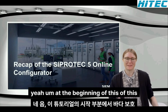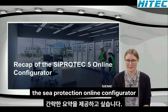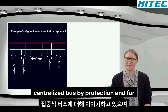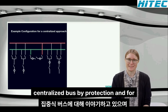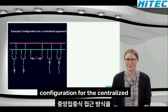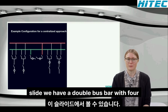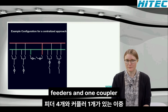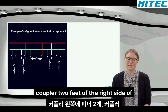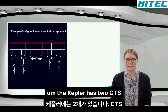At the beginning of this tutorial, I want to give a short recap of the SIPROTEC 5 online configurator. And today we are talking about a centralized busbar protection. And for this, we prepared a small example configuration for this centralized approach. And this can be seen here on the slide. We have a double busbar with 4 feeders and 1 coupler. 2 feeders on the left side of the coupler, 2 feeders on the right side of the coupler. And the coupler has 2 CTs.